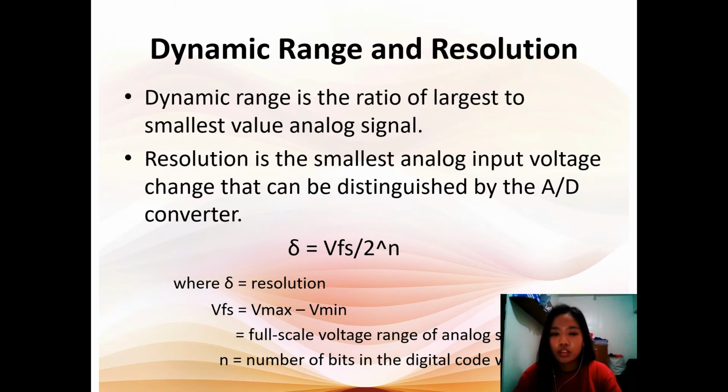VFS is the full-scale voltage range of the analog signal, which can be computed by the maximum voltage or peak voltage minus the minimum voltage, and n is the number of bits in the digital code word.